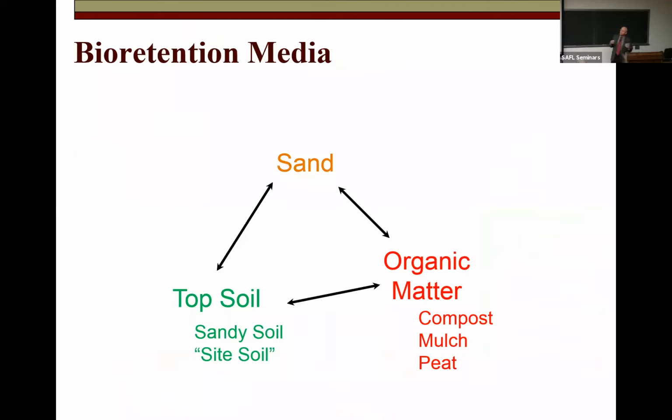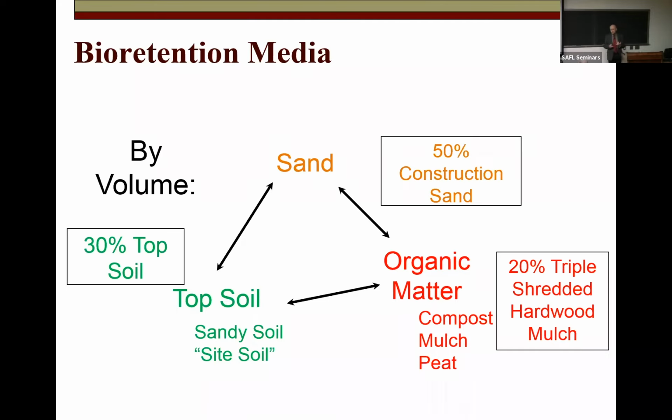So you see bioretention all over the place. When we talk about bioretention media, generally, characteristically, it's going to have some amount of sand, some amount of topsoil, and an organic matter source. Different jurisdictions are going to have different recipes for your bioretention media. In Maryland, we've settled on this basically as a recipe. It's tended to work fairly well for us.